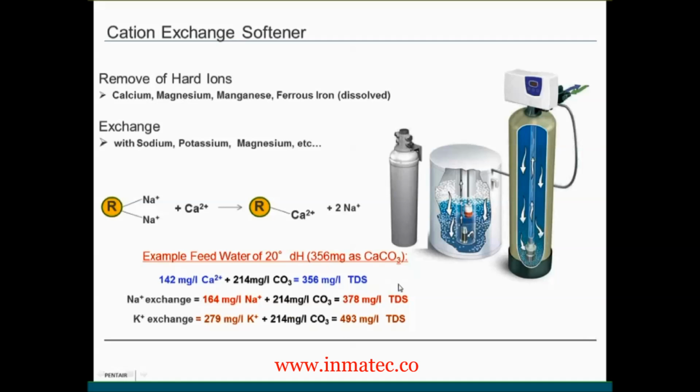There is a slight elevation in TDS when using a softener because we are putting 2 sodiums in for every calcium. And this increases the conductivity of the water, which shows up as TDS. This is normally not a significant increase.